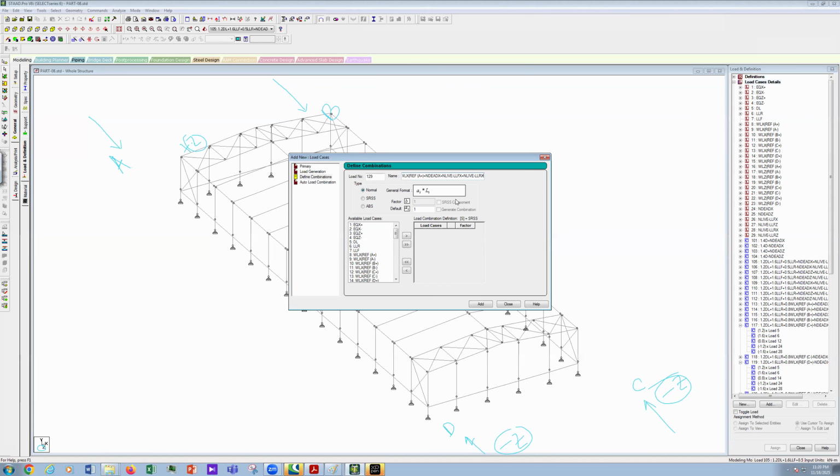And we have our original load combination factor, which is 1.2 dead load, 0.5 roof live load, and 1 floor live load, and 1.6 wind load along x direction, positive x direction, with reference point A. Okay, so for reference point A along the transverse direction, wind force is going along positive x direction, so it will be a plus sign. Okay, you can see here.